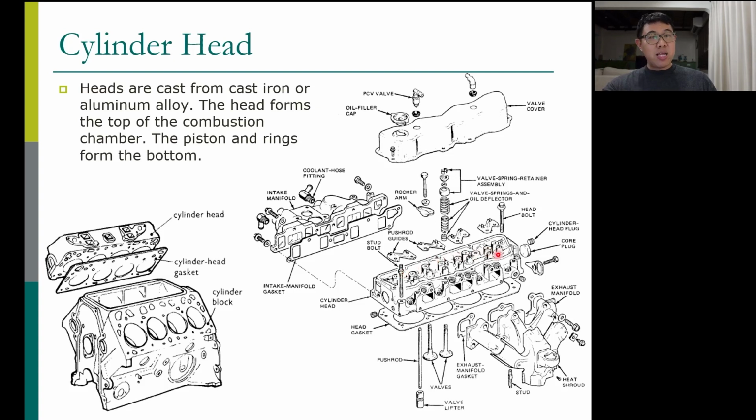Valve train needs lubrication, so we have to put lubricating oil there because the camshaft is moving, the valve is moving, right? So we have to circulate the lubricating oil there. Therefore we have to have a cover. This is called valve cover. Cylinder head has valves, this is valve cover.